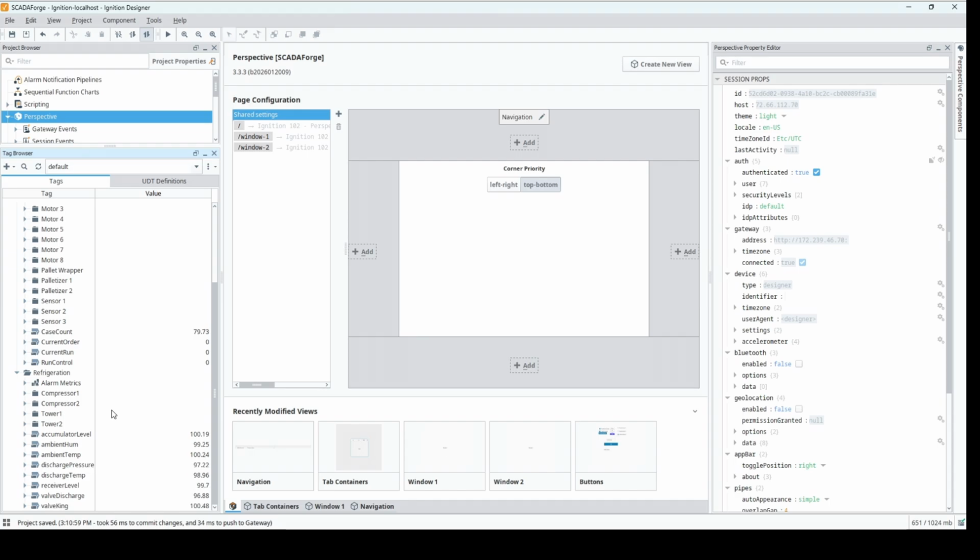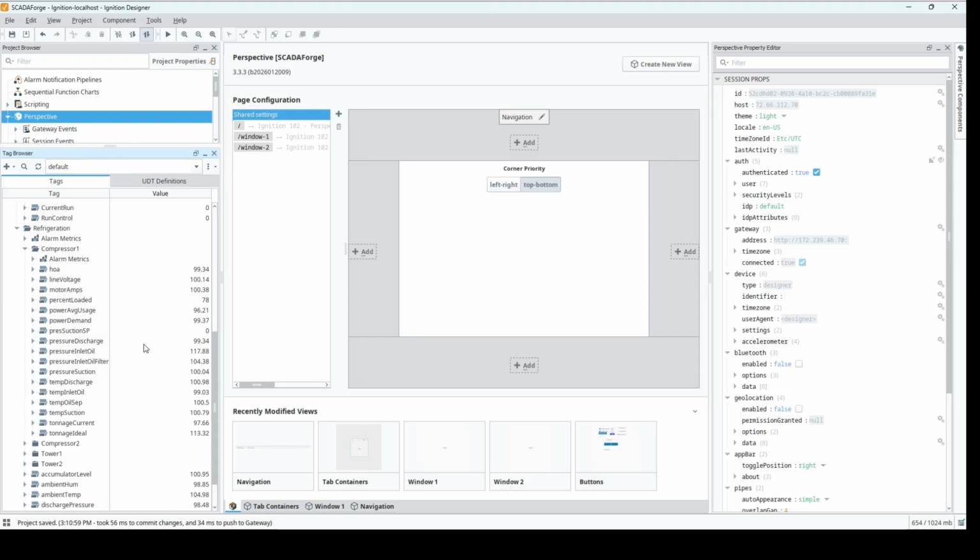So now we have the ability to set up things like alarms, tag history, etc., as we need to, based on our process requirements. So that covers devices and getting something set up in Ignition so you can pull tags across. And then in future videos, we'll use this data to make some interesting screens, as well as get into the design challenge and the gold certification prep material.